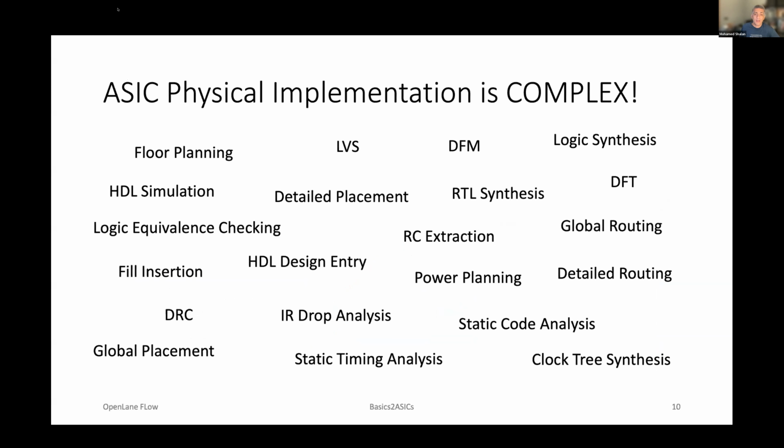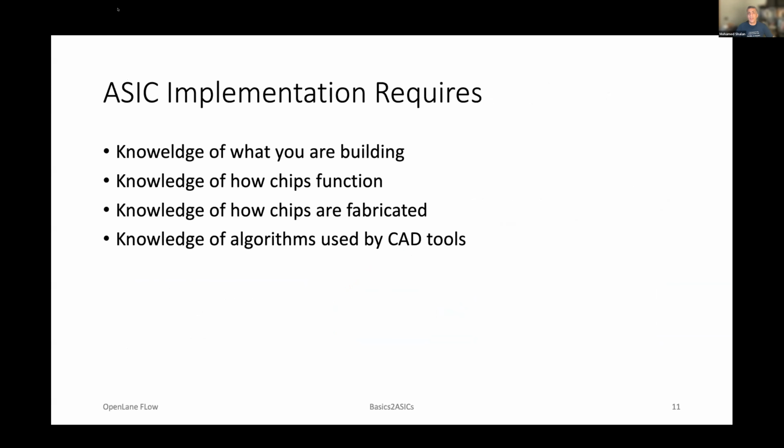So ASIC implementation requires lots of knowledge about what you are building, the functionality you want to build, how the chip functions, and how chips are fabricated, because when the layout is generated, it has to be manufacturable, which means it has to honor manufacturing rules.